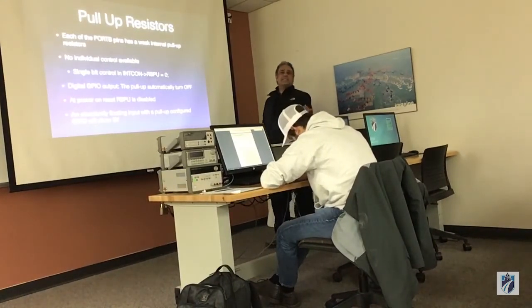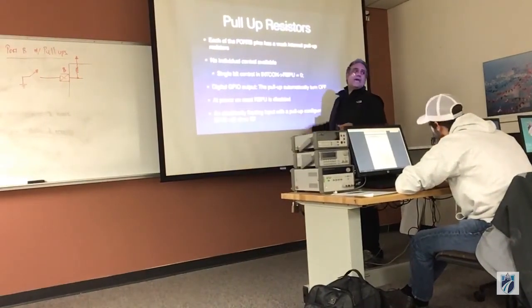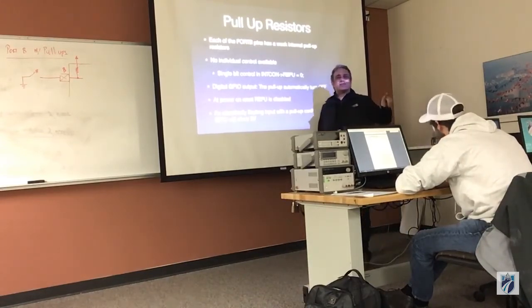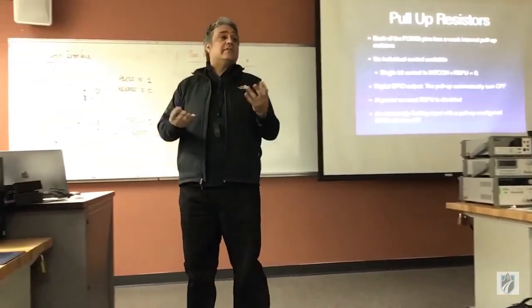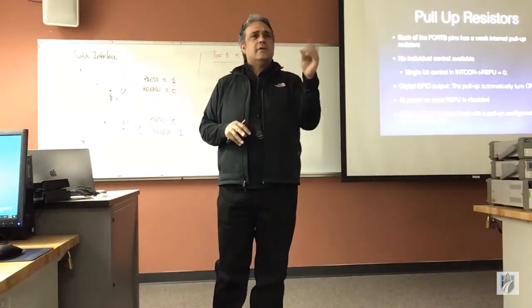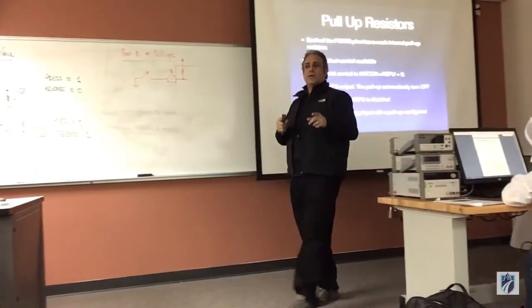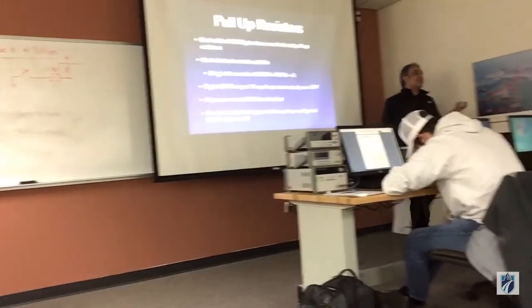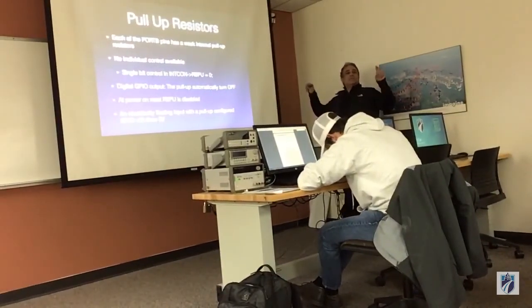The other part is that the moment, let's say that you engage the pull-up resistors and then you make one of the pins an output. This is a great question for an exam, by the way. This is always a great question for a test. It's actually right there in the data sheet, but we don't like to read it sometimes. So here's the deal. If you make the pin an output and at the same time you have pull-up resistors, the pull-up resistor gets disengaged. It actually gets turned off. So even though there is no individual pull-up control, in some sense there is.